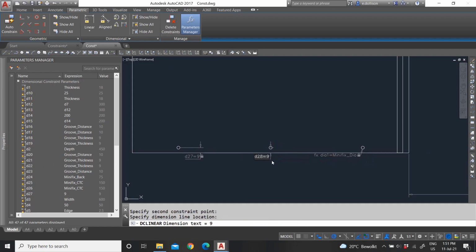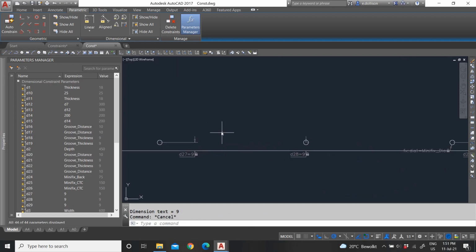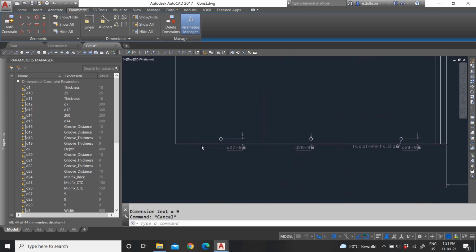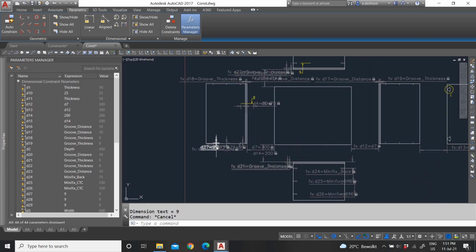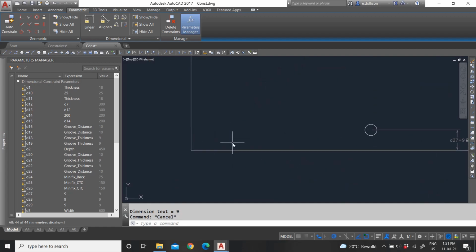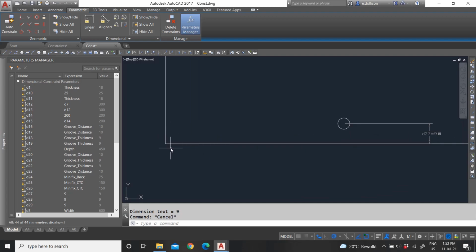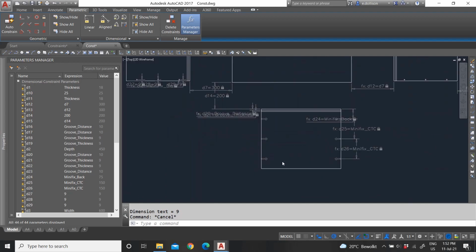And this would be the distance from my center point, or the center of my pin, the minifix pin, to the end of the panel. So basically how I design it is the bottom panel has to be a distance of 1 millimeter to the bottom. So when you're actually watching the cabinet from the front, the bottom panel is 1 millimeter higher than your side panel so that you don't have any visible edges on the outside.